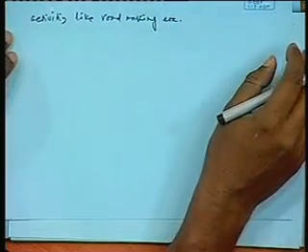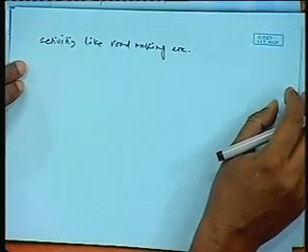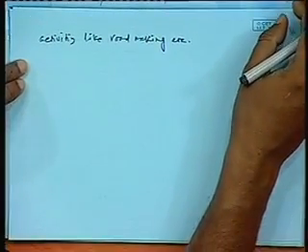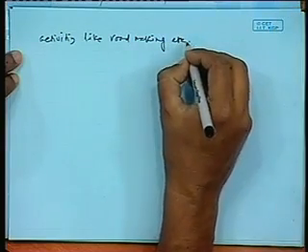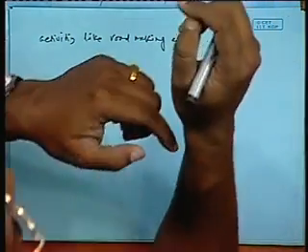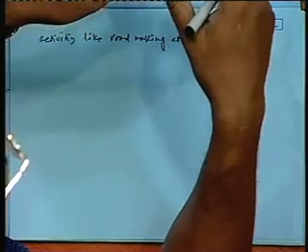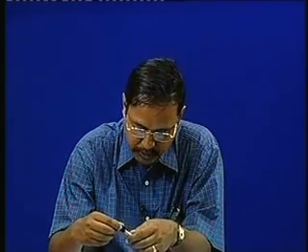The sediment ponds serve a great purpose. All these serve a great purpose, helping greatly in reducing the erodibility of soil, and thereby reducing the impact of rainfall on the slope, to reduce the erosion, as well as to arrest the fine particles.